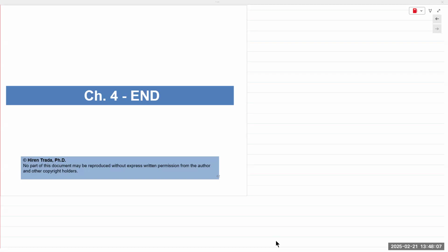Okay. The pinout configurations that you see here, pin numbers 1, 12, 4, 7, 13, 3, 2, all of that remains the same. My suggestion to students always is divide the circuit in half, like right down the middle, right here. And create these 2 with 2 JK flip-flops inside each chip. Create them separately because they're the same pinouts. It gets confusing. Once you create these separately, then take a single piece of wire and connect pin number 5 of the first one to pin number 12 of the second one.